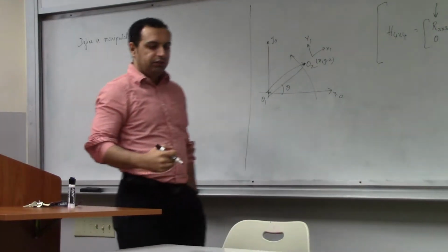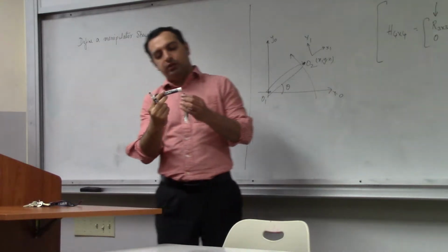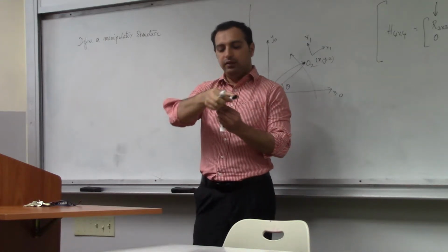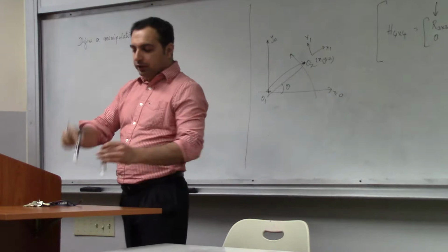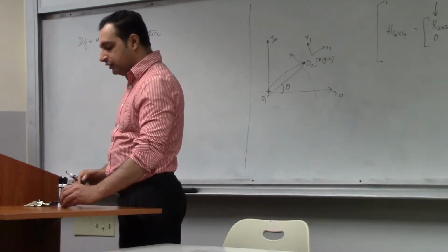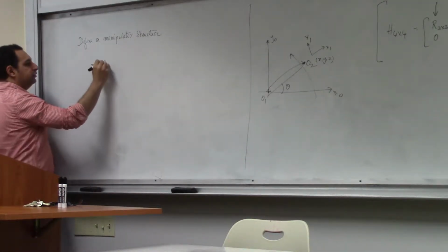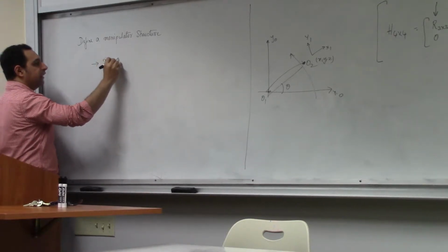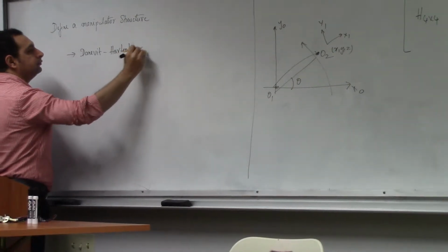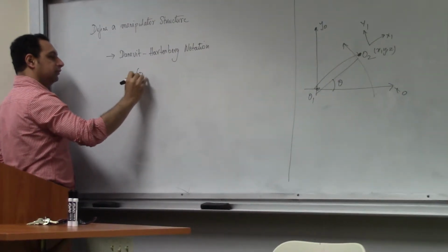it is a definition of how links are arranged. For example, you could have links arranged perpendicularly, but perpendicular does not specify everything in 3D space. It could be any one of these angles, or it could be just an offset in a direction, and unless specified you cannot tell what it is. So we use a mechanical notation known as Denavit-Hartenberg notation, or we simply call it the DH notation.